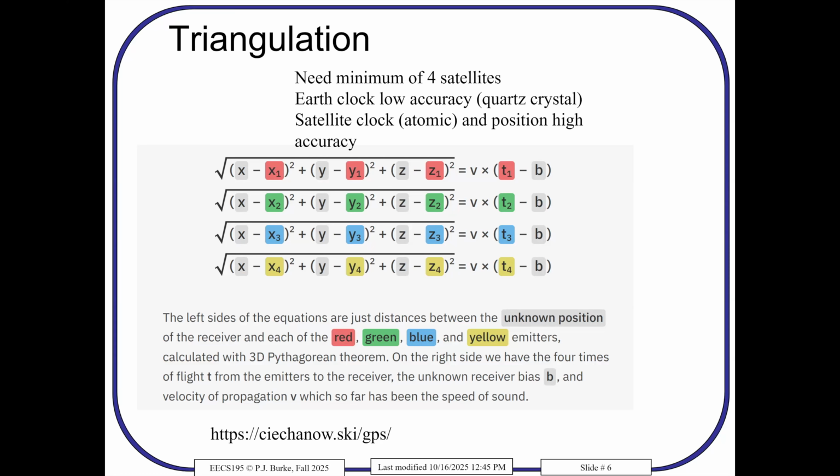Yes. There could possibly still be RF interference. That is possible. However, we do have error correction codes built in. If you're not familiar with that, I can give you a short version. When you send an n-bit signal, it has to have a certain parity. It's either an even or an odd number of bits. And you always transmit, let's say, where it's even. And if it comes out odd, that means one of your bits has flipped. So you throw those out. So there are ways of mitigating RF interference with error correcting codes.